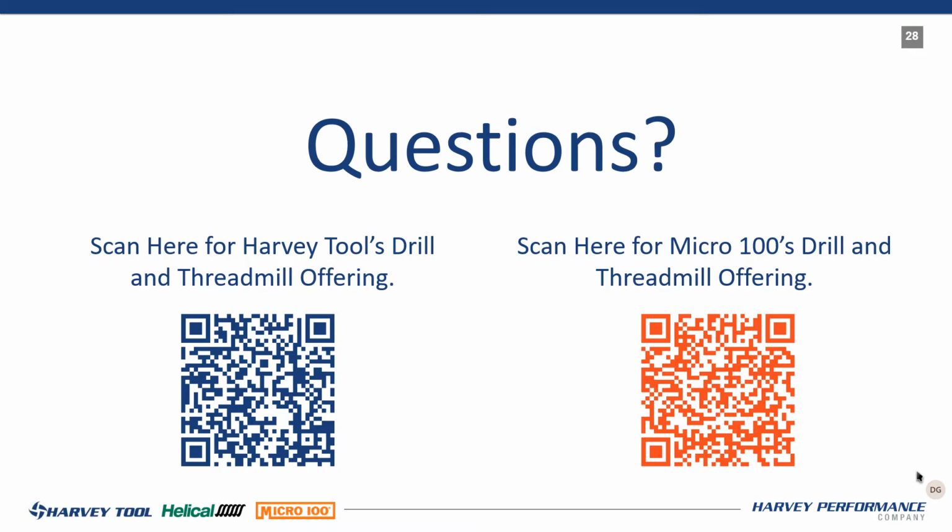It's in the ballpark depending on what you're doing. Remember, this is a generalization, and when it comes to pecking, depending on what tool you're using and how deep you're going, I'm going to say it is a science. And I have solved a lot of problems. Let me just point this out here: if your drills are breaking and it's a non-coolant-through drill, start messing with your peck. I'm telling you right now, 100% of the time, if your drills are breaking and it's non-coolant-through, start messing with your peck.